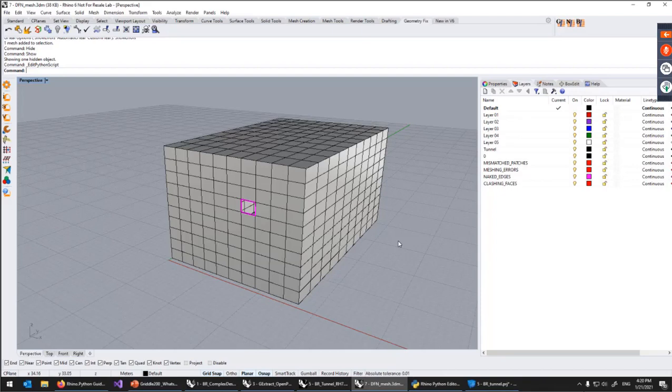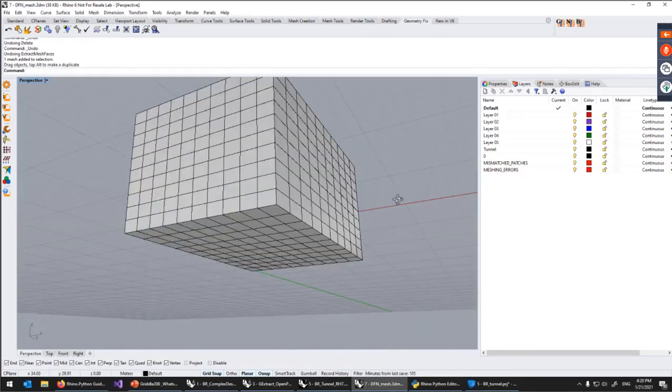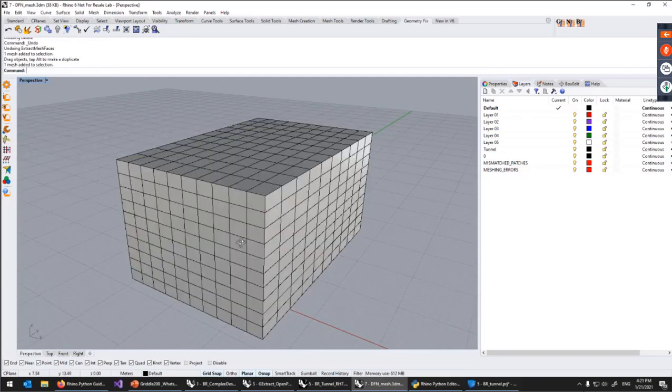The unstructured volume mesher, GVol, operates on surface meshes. Essentially, surface meshes have to create a watertight domain, like you see here. Let me undo this. You see, this is a watertight domain created out of essentially 6 perpendicular meshes.